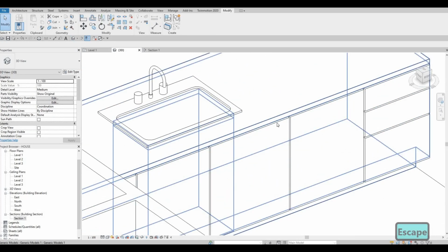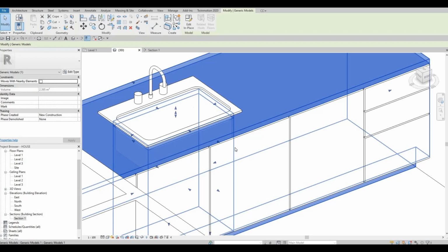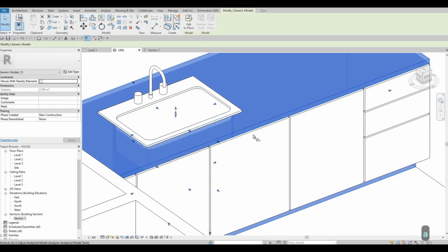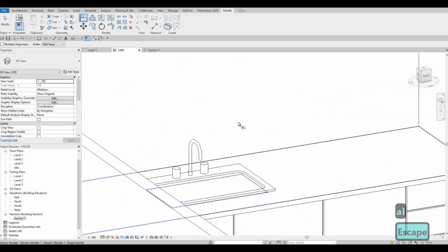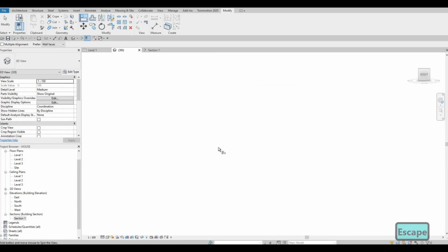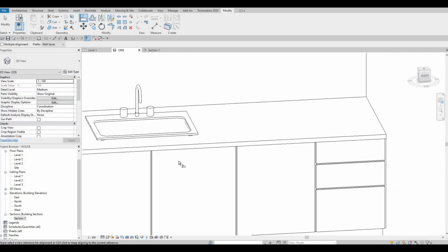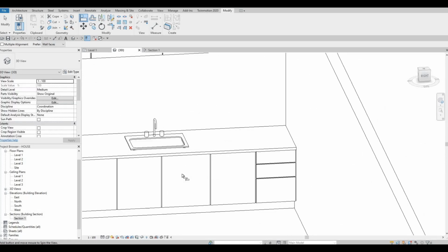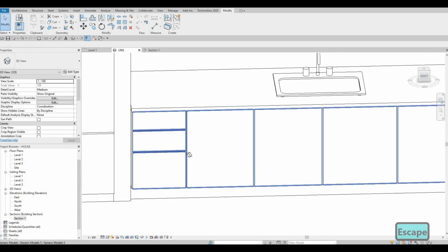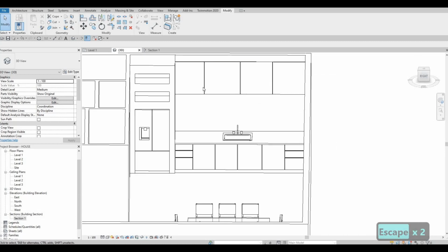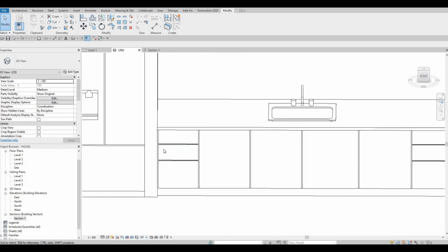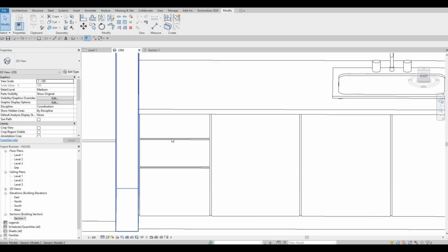We might need to extend this top. So you could just click on the top. We could use AL as well. So to the face and then to the face, so that we have some space there. Now what I'm gonna do is, let's do something different here by creating some handles. What I'm gonna do is a very simple handle. So we could just use